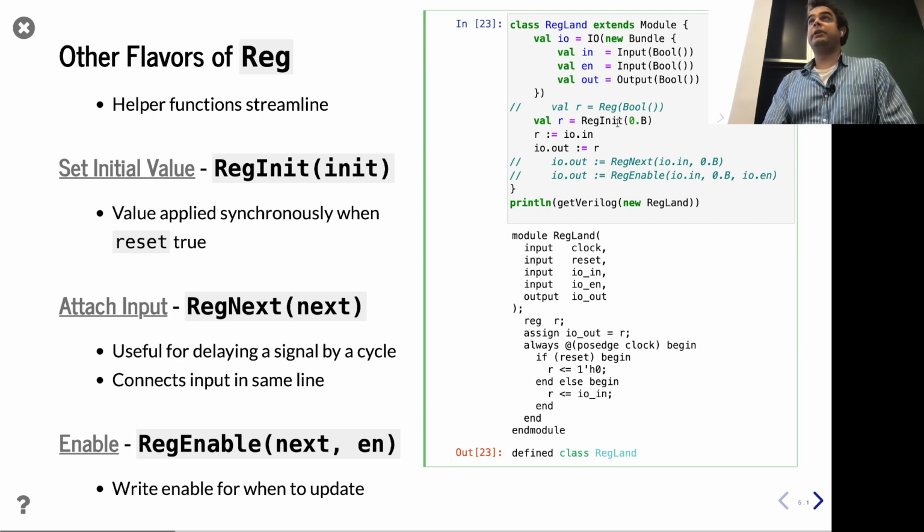Yeah, so let's be clear, right? There are edge-triggered flip-flops, which is what Chisel works on, in particular positive edge-triggered flip-flops. And so to do a negative edge-triggered flip-flop, you would want to have an inverted clock to then get the negative edges. That way, it's still positive edge from the point of view of the clock, it's just a negated clock. Now, perhaps what you're asking is, rather than a flip-flop, maybe I want a transparent latch. That's something that's actually not in the language, right?